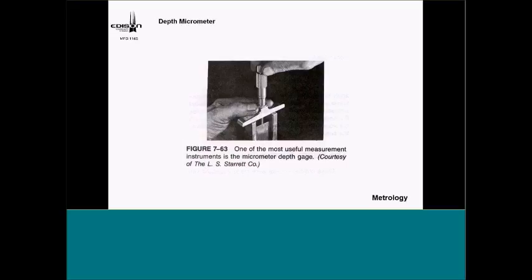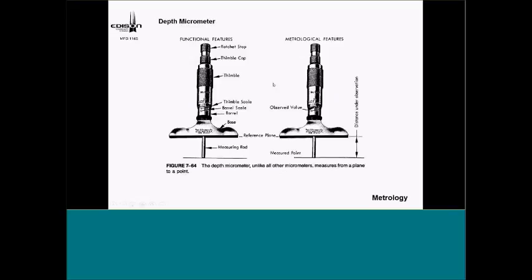Okay, then depth micrometer. How do you read it? We're going right to left instead of left to right. And again, we talk about the various parts: thimble. I have enough of these and I'll pass them out. Every student will have one. Talk about the ratchet stop.